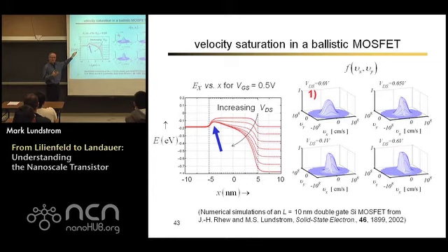We're assuming that this source is a very big region with lots of scattering. There is a Maxwellian velocity distribution there. Same thing for the drain. The positive half of those electrons can hop over the barrier and get into the channel. All of the positive x velocities in this came from the source.